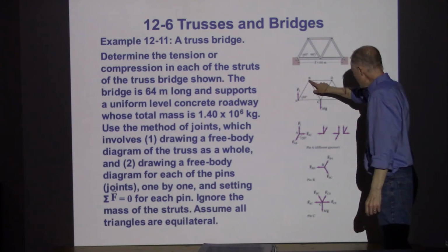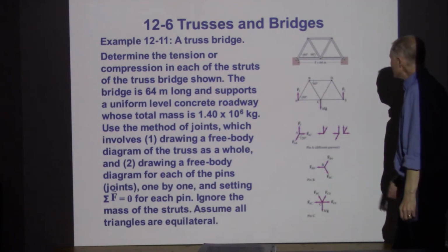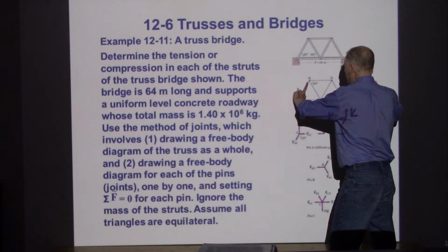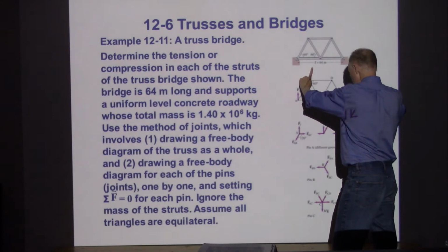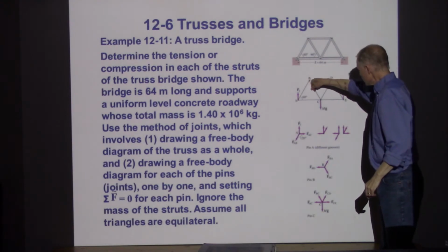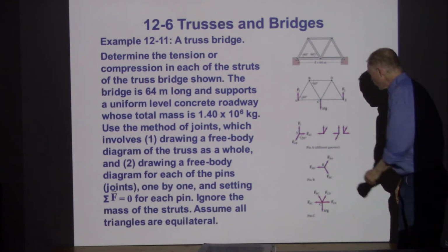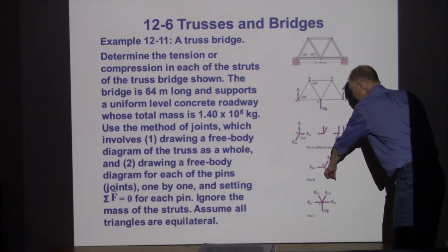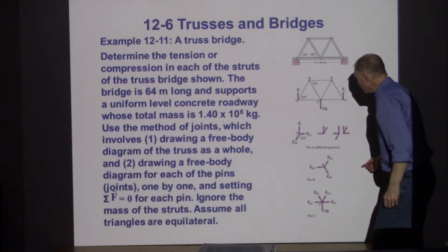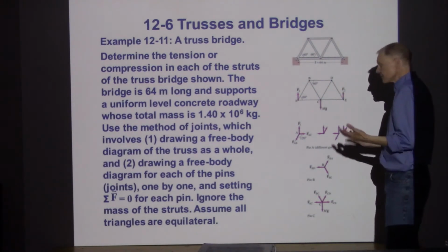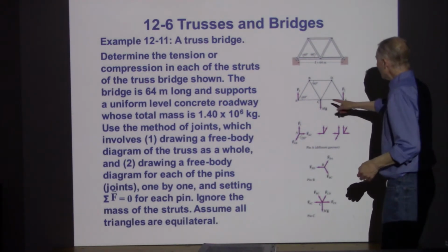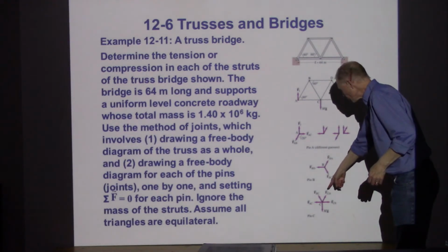When we get to point B, this support structure here is going to be pushing up on B, and that's listed as force BA. And then here, this is going to be pulling down. So force BC is pulling down on that point. Now if BA is lifting up in this direction and BC is downwards, then BD has to balance those out. And so BD would need to be to the left. And then finally at point C, we have an mg force downwards.